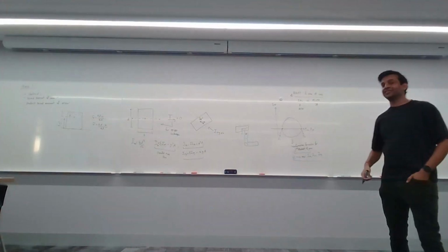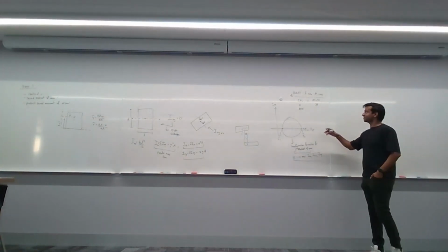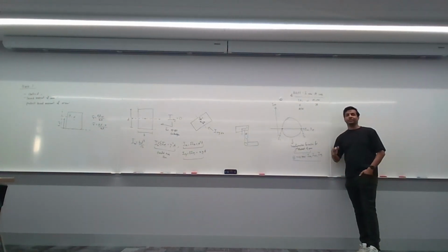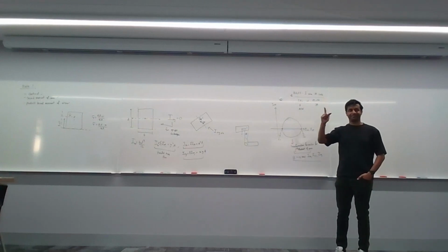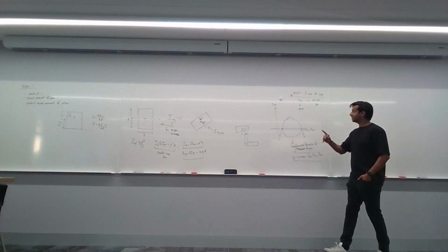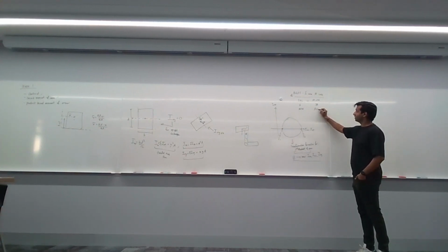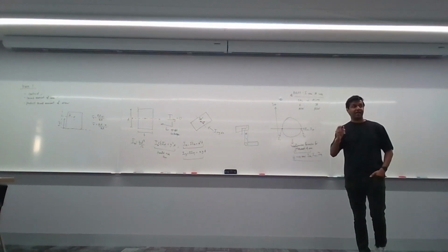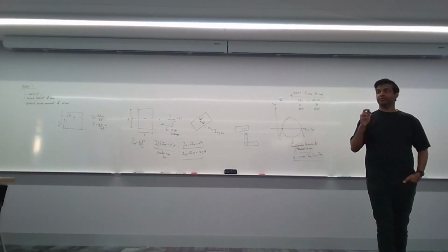Okay. Now this is why I like to bring this up, because what you're referring to are the rules of the stress and strain Mohr circle. The stress and strain Mohr circle, yes, they are opposite directions. But for the I value Mohr circle, it's actually the same direction. An anti-clockwise rotation in real life is also an anti-clockwise rotation in the Mohr circle.